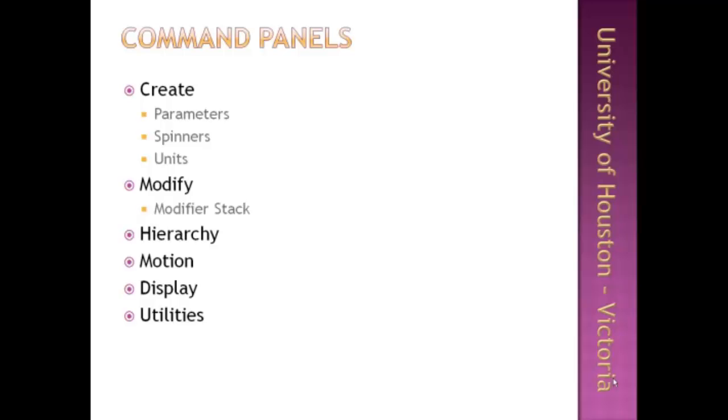Units are important when a scene needs to be made to architectural or engineering specifications, and when the scene will be shared with other users in the project, because discrepancies might occur if people are using different kinds of units. I showed you how you can change the units. You can go to tools, then units setup, and change the units options that you have.